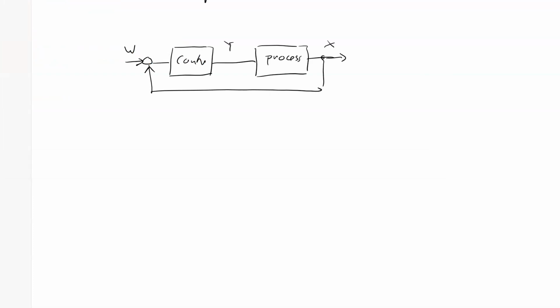Okay, how can you work with this program? You should know that the process can be selected by a menu point which is called ADC cards. Why is this called ADC cards? Because you can run real-time systems, and with ADC cards you select that card which is connected to your PC, and this ADC card then is connected to your process. So a process includes ADC and DAC card, and here you can select them. This of course needs hardware.